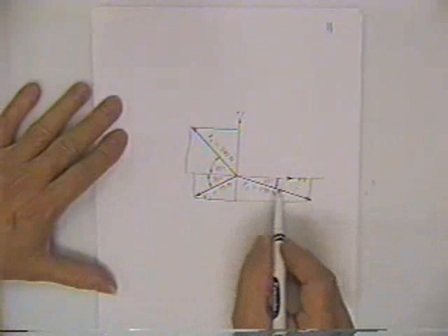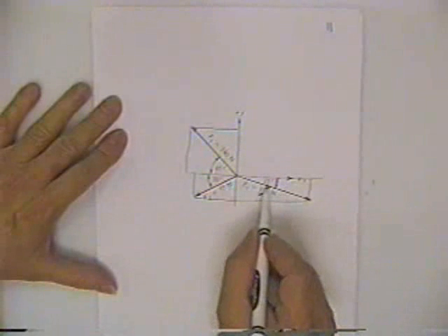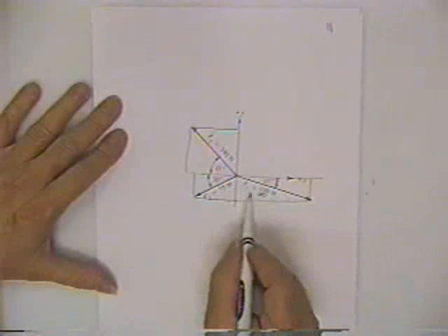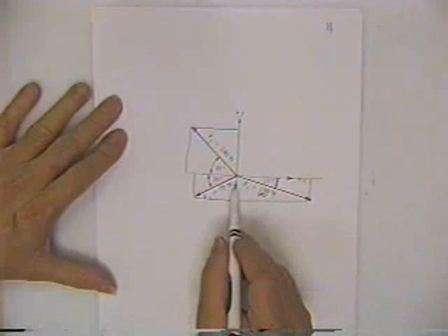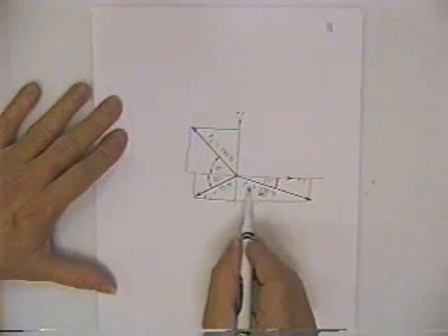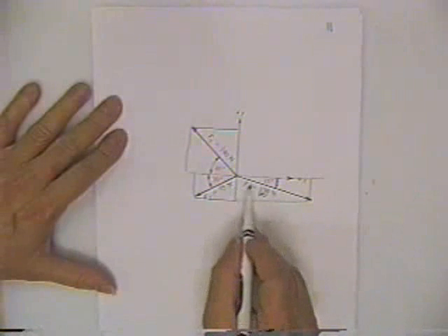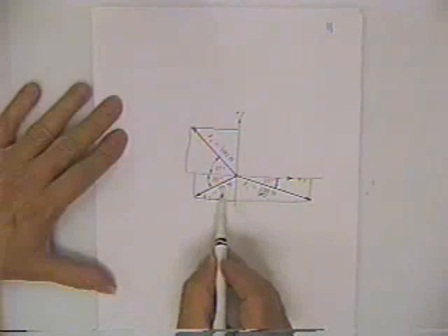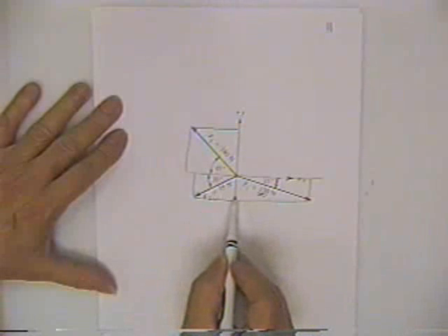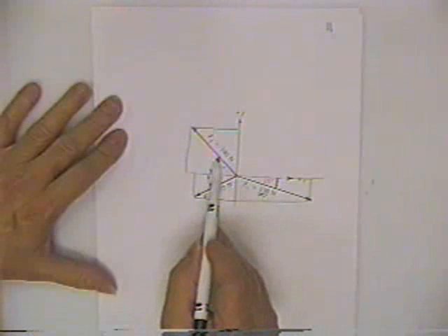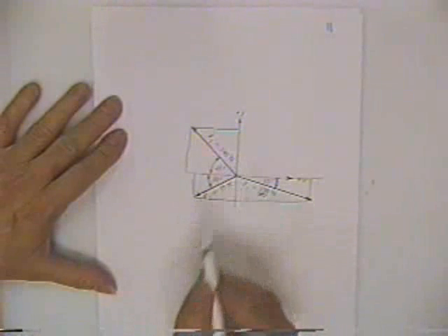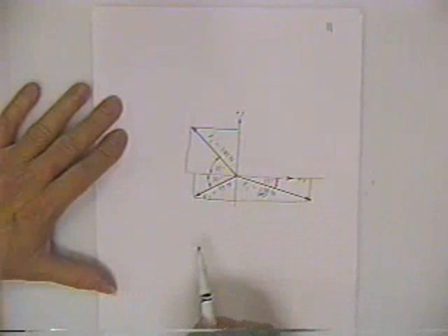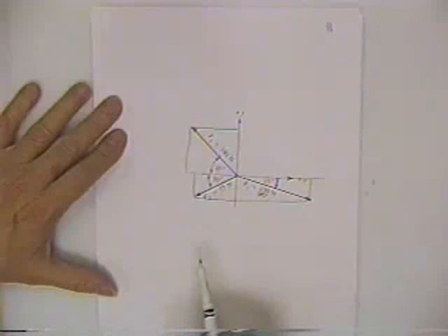To find this horizontal force, you would multiply the force times the cosine of 15 degrees. To find its vertical, you'd multiply 130 newtons times the cosine of 75 degrees, the complement of this 90-degree angle. Then you would have the 75 Newton force times cosine 30 and cosine 60. Then you'd have the 140 Newton force times cosine of 45 and cosine of 45. And I don't care if we work out those numbers as long as you know what we're doing here.